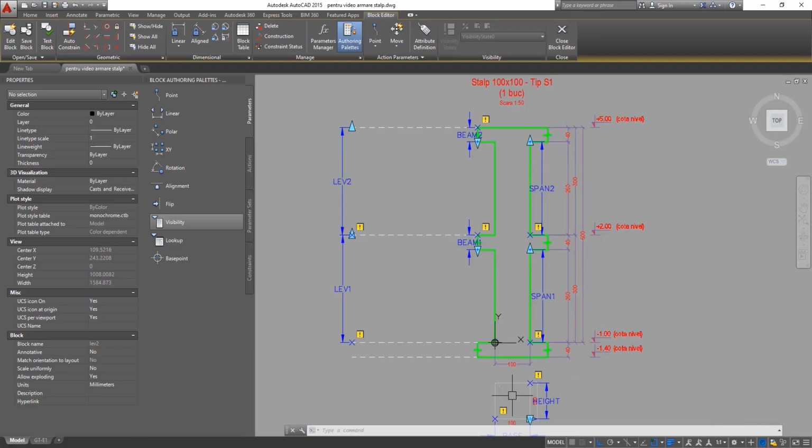And afterwards this line will be deleted and purged, because the final drawing will reach the client without these ones, but a normal drawing. The idea being of constructing it rapidly by using dynamic blocks and Lisp command. Okay, so the main philosophy is to construct it rapidly by these techniques, and afterwards placing the drawing to the client, just a normal drawing. Okay, so this is just an internal issue for us to construct it rapidly and precise.